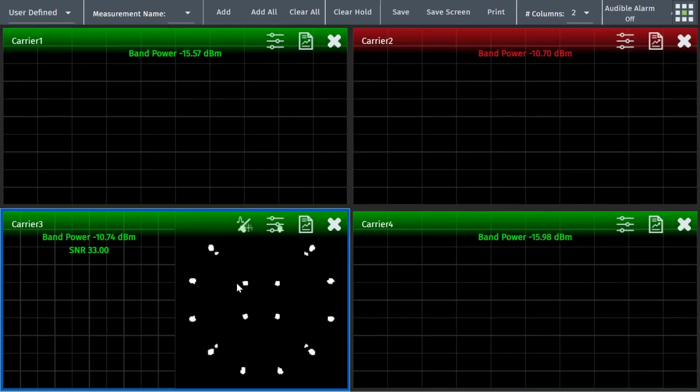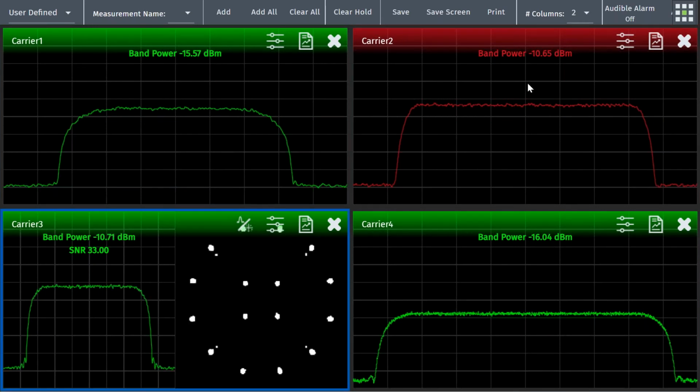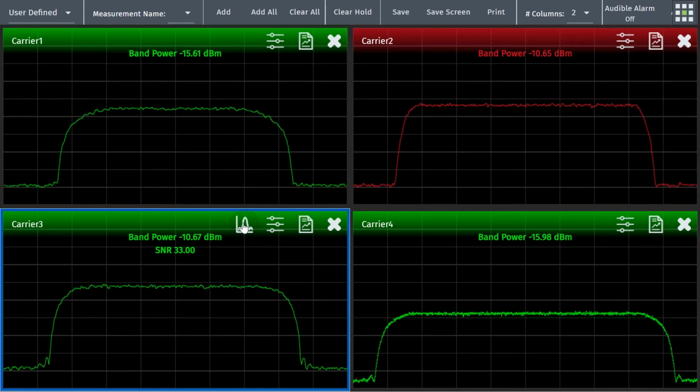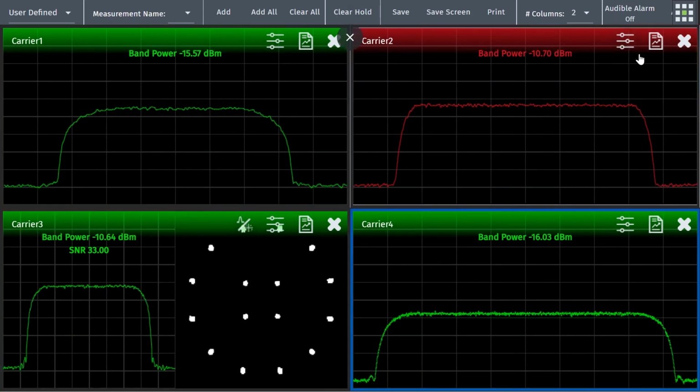Yeah, so you can see similar Constellation displays to what we were looking at on the signal analyzer screen, and again, in a tiled display. And here, like I was mentioning earlier in the slide deck, if you have both Spectator and Detector, you can look at both, and you can do some mixing or matching. If you're only interested in the spectrum, or only in the constellation, you can toggle back and forth, take a deeper dive into the signal, and just display what you're interested in.